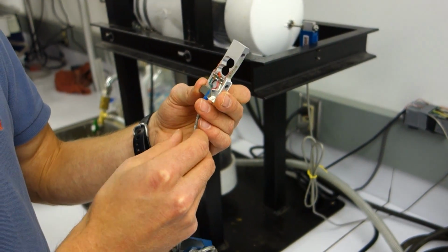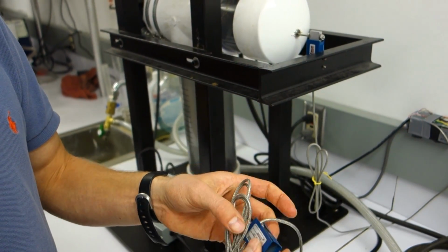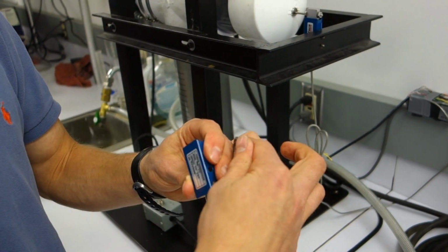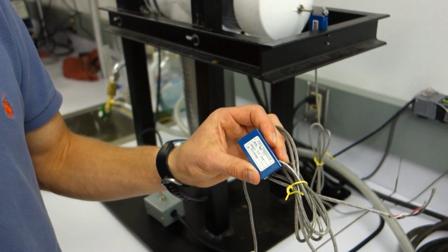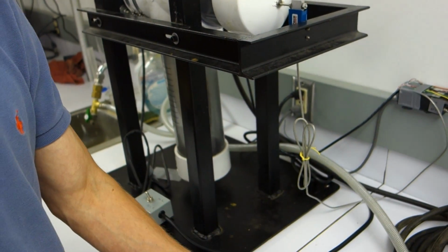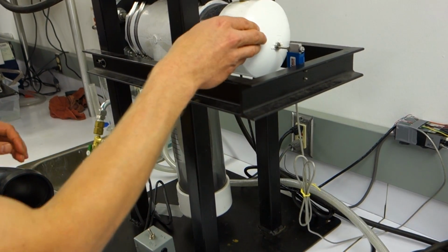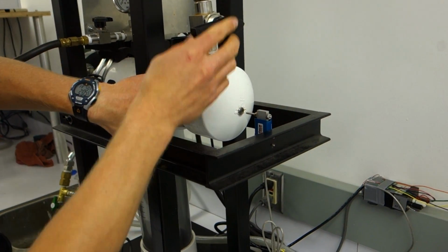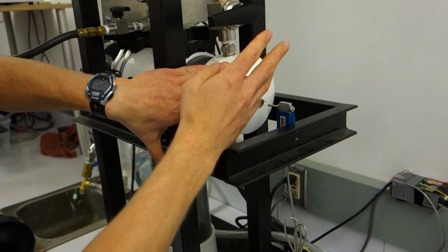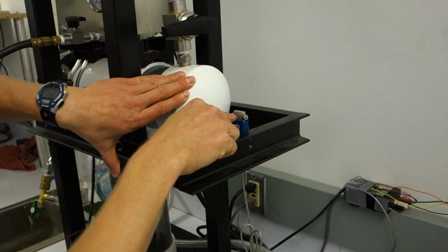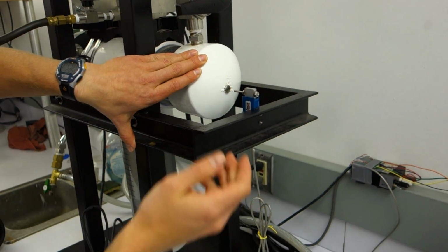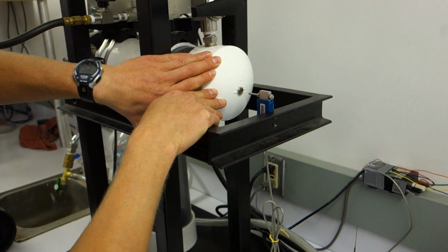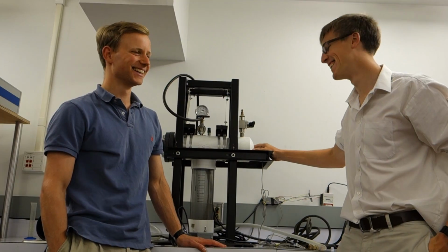They are also pretty sensitive, so this guy is maxed out at 10-pound force. So we can break it if we apply a force greater than 10-pound force, and that's not hard to do. So if we push it to hold it away from the strain gauge, I'll feel more comfortable filling the whole thing up with water. But we have to be very careful not to let go because we will plastically deform the flexible element and then break the strain gauge.